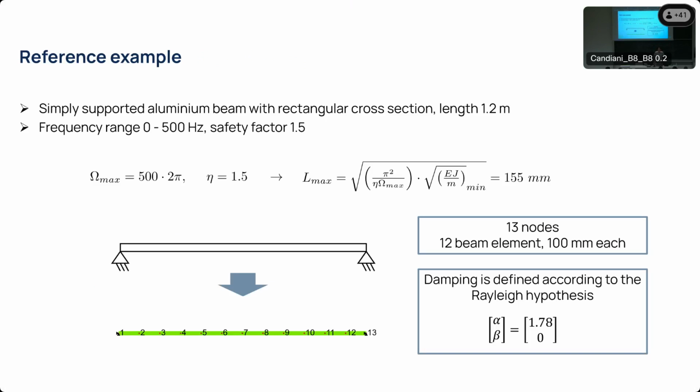We already saw that the finite element method allows you to model a structure even if it's very complex. Why should we use anything related to the modal approach also if we work with the finite element method? For that, I can just give you an example. Let's imagine that you are designing a skyscraper or the Messina Bridge or any possible structure that you want to investigate. You make your finite element model, and at the end of the discretization, your finite element model has 100,000 degrees of freedom.